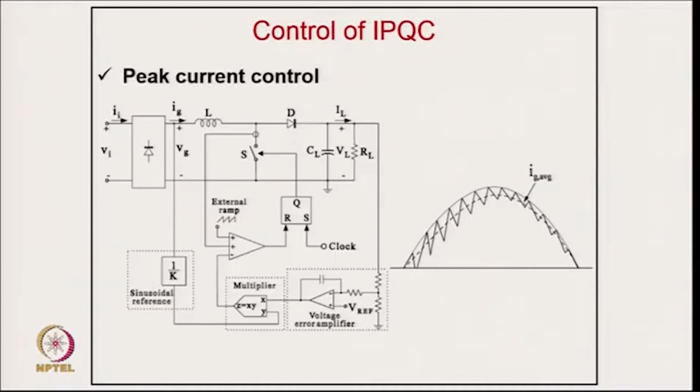So that you get power factor correction along with reduced harmonics, and of course the diode rectifier does not have any reactive power burden. This is quite a popular converter, which we call the PFC boost converter, power factor corrected boost converter, extensively used in plenty of applications, because the major advantage of such converters is that you get a regulated voltage irrespective of varying input voltage. The input voltage might vary, like in India we can have 170 to 270 volts, but still you can maintain the output voltage typically at 400 volts, or 380 to 400 volts.